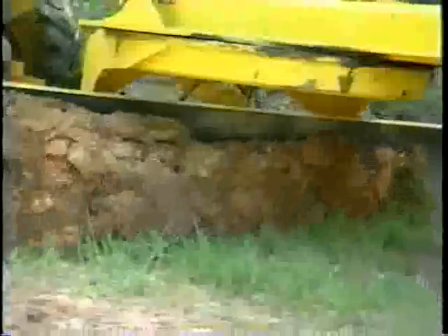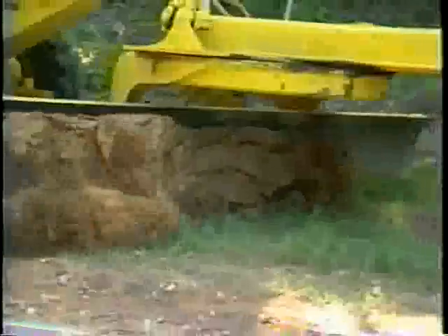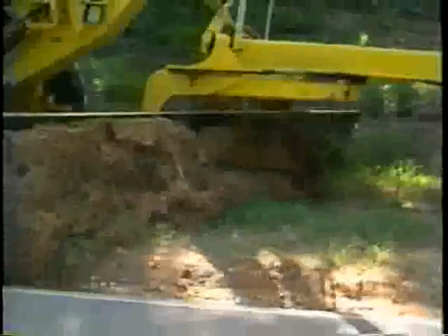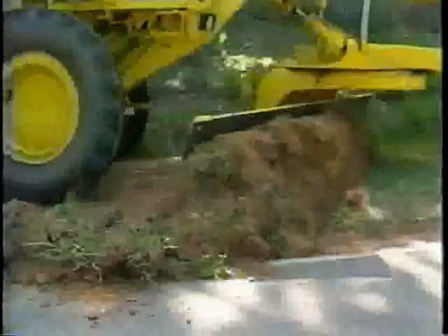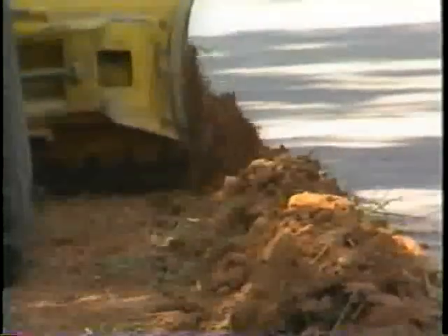Cut just enough material on the first pass to remove unevenness, ruts, and depressions that exist. Pull the material from the outside of the shoulder at the front slope of the ditch. The material is neatly windrowed at the edge of the pavement. Note that the windrow is placed outside the rear wheels of the grader. All ruts, unevenness, and depressions have been cut smooth during this first pass.